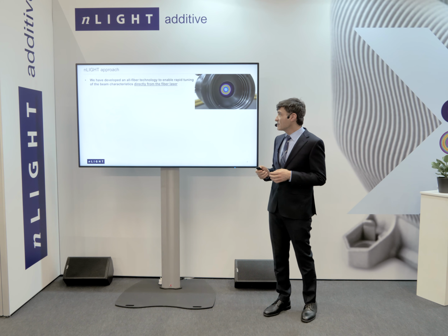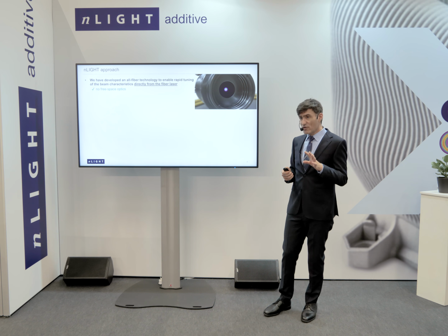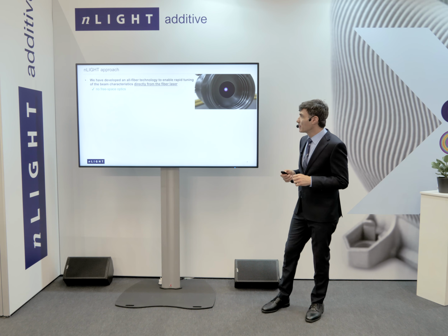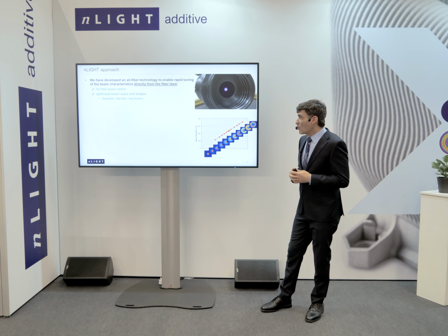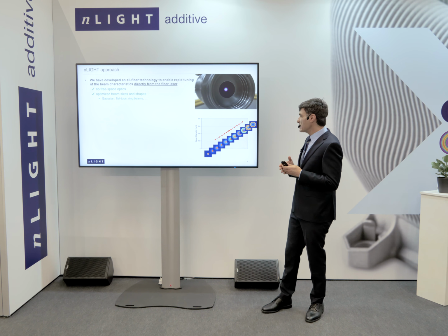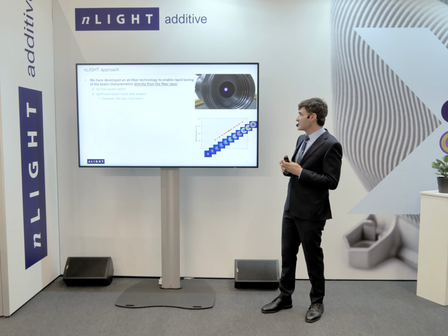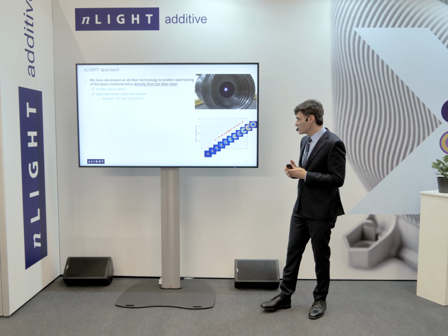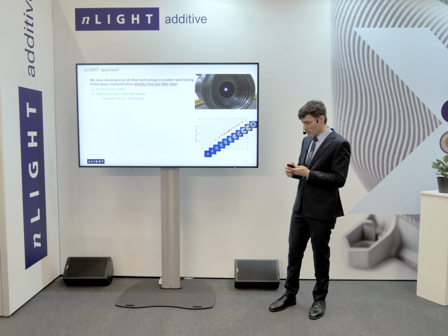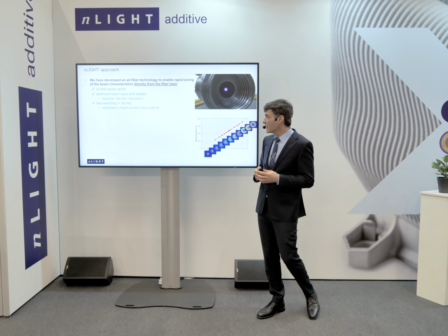The key points of this technology are that there are no free space optics. This is done all in the laser, all in fiber. We have a wide variety of optimized beam shapes and sizes. The Gaussian that I mentioned, also flat tops and ring beams, and they're different versions. This was the single mode version. Here's a multi-mode version where the beam goes between a 100 micron flat top and a 330 micron ring.